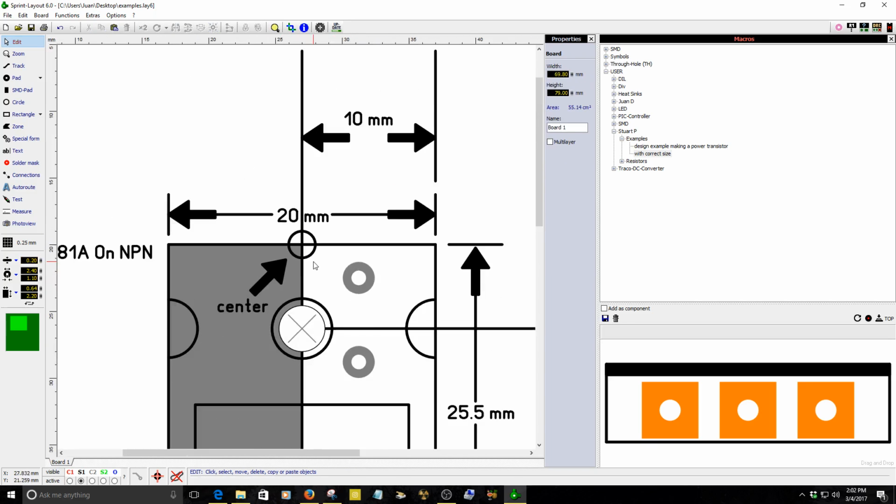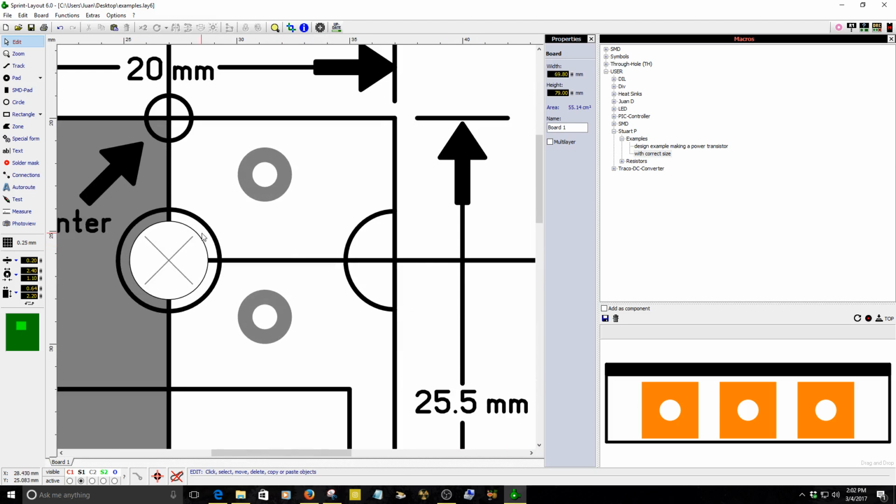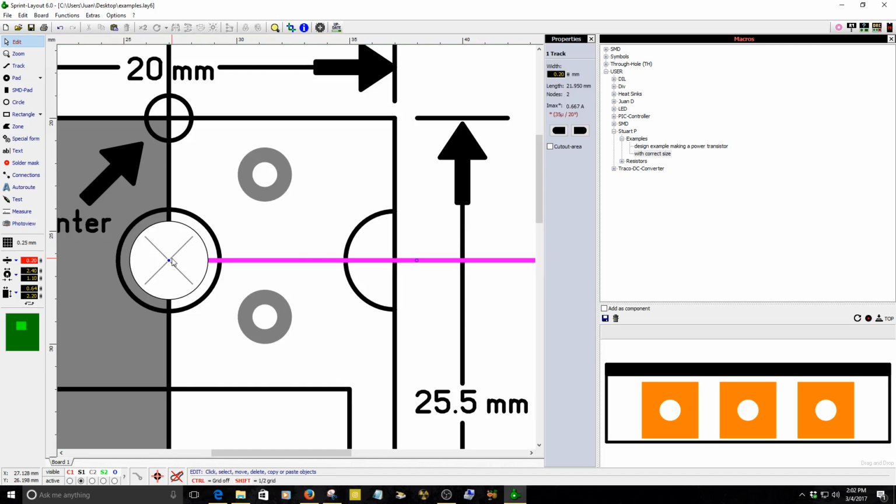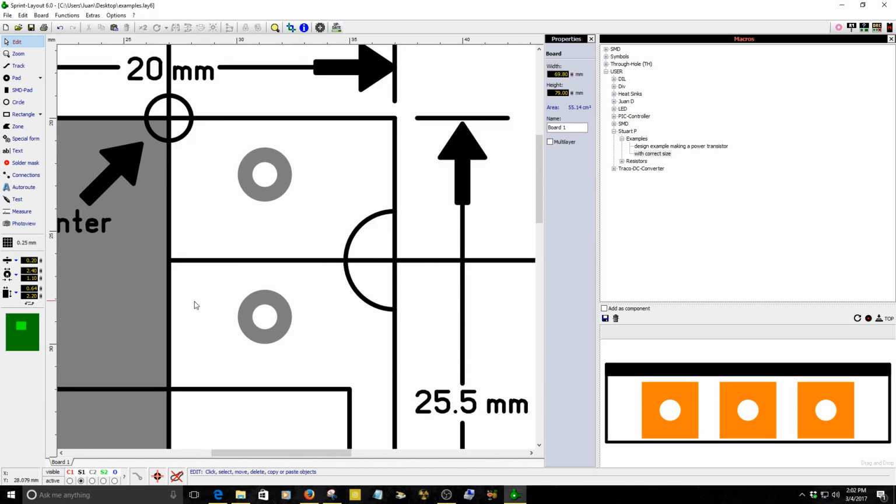All right. So right now, what I do, well, I'm gonna delete this drilling hole. This is a 3.5 millimeter drilling hole. So both numbers need to be the same. That means they're just gonna drill a hole through the PCB without having any solder area. So it's not gonna have any solder. All right, so now I'm gonna delete this one here just for the example. I'm gonna delete this one too, so it's not really needed.